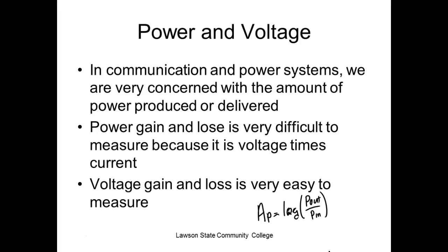Notice you got what we call a reverse Polish calculator, where you actually put the equation in there. Standard entry calculators, we have to work from the parentheses back, right? Anybody that has algebra knows that. So what we would do here is measure the power out over the power in, then whatever number we get, we take the log of that number, and then we multiply it by 10.